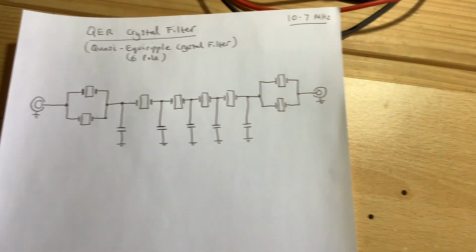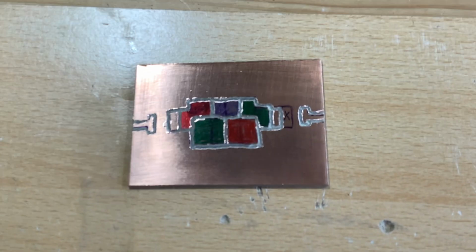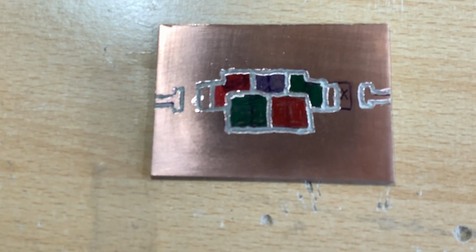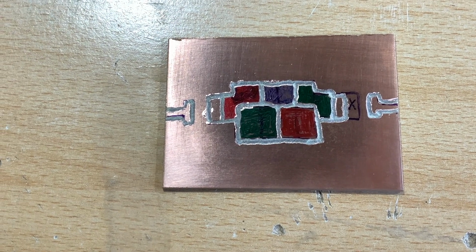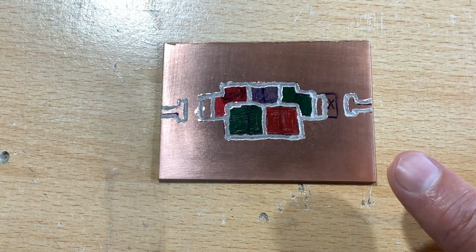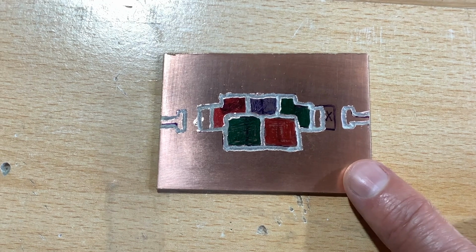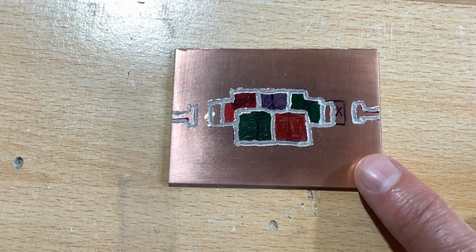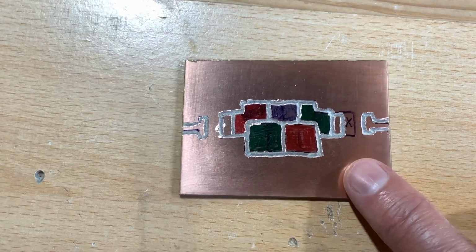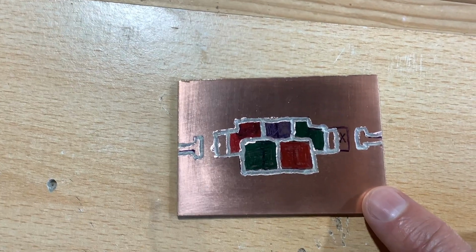Now, what I then did was create my board. And so here's my little copper clad board. All the usual rules apply. Before I used this, I went over it with some fine wire wool to remove any lacquer that might be on it. Then I went over it with the multimeter to make sure that it's nice and conductive over the whole surface. I sawed it in half, as you can see, roughly.